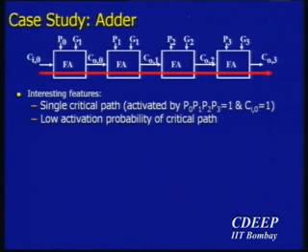But the question is that that's not good enough, right? That 75% of the time I'm really doing 2-cycle operations. But if I look at bit number 8 and 9 at the same time, let's say, then 0, 0, 0, 0, no carry propagation, 0, 0, 0, 1, no carry propagation, 1, 0, 0, 0, no carry propagation. So you can come up with a condition, right? If you look at 3 bits, in fact, the probability is going to be even better.